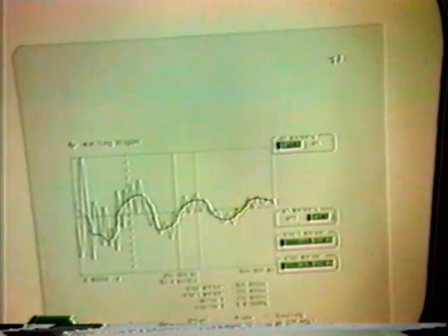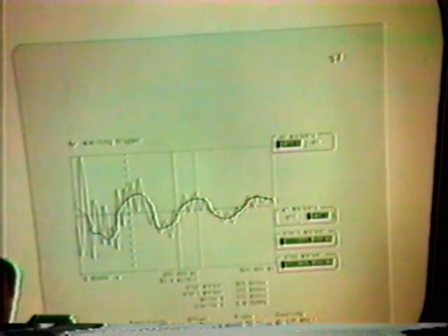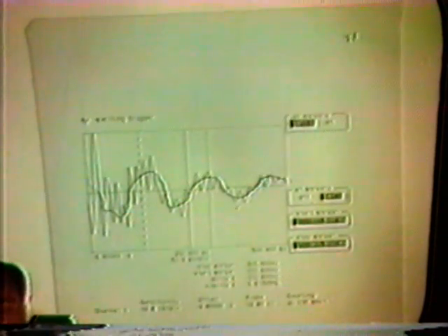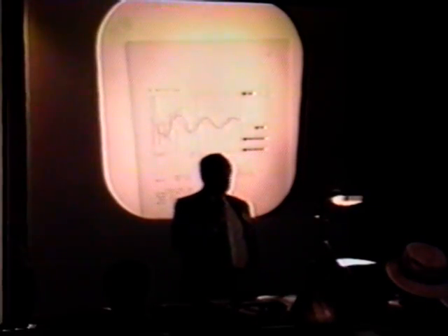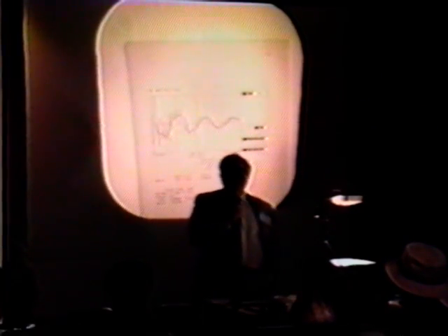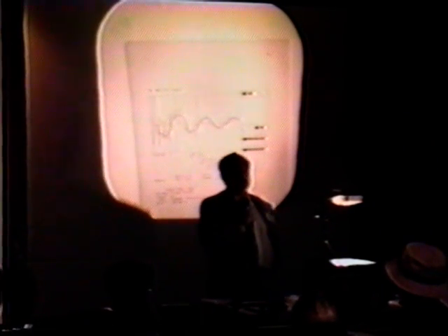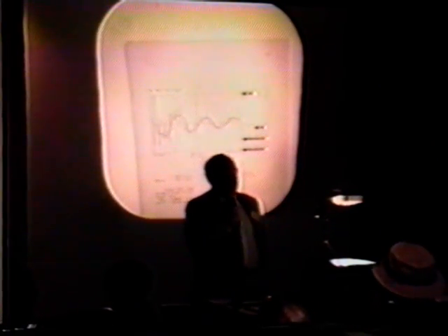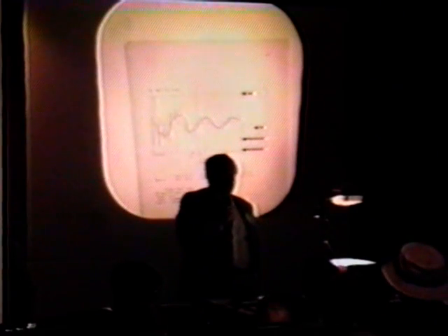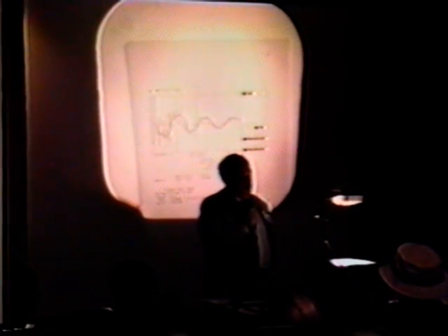Very clearly, you see the ringing, and it is modulated by the spark frequency. Now this is a very good situation, because if the ringing frequency is present, we can calculate the energetic situation of the circuit according to the classical theory. So we have a damping oscillation modulated by a higher frequency there.